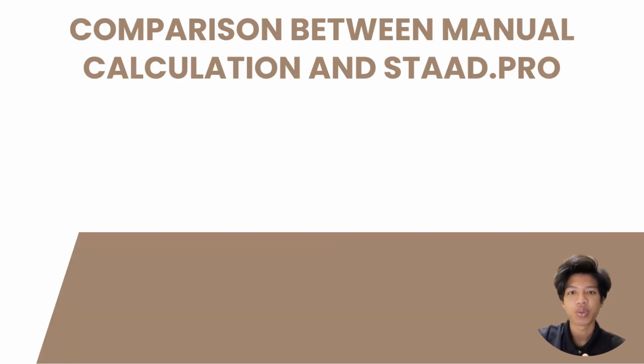This is the difference between manual calculation and StaadPro. In manual calculation, we have a 2D simplified equilibrium equation, approximate diagram, mid-span formulas, and manual capacity check, approximate and conservative. In StaadPro, we have a 3D frame, automatic frame analysis, detailed beam force and diagram, full displacement, force provided, design separately, and it includes the 3D effect.